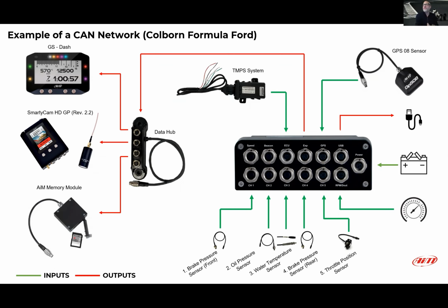Now, someone's mentioned in the chat that, unfortunately, I'm missing some of the ECU channels that are available on the ECU, like oil temperature, gearbox. I think there's a few ways of being able to do that. The first is we may be able to ask for an ECU mapping to be created. If it's too old a vehicle, you may have to use sensors.